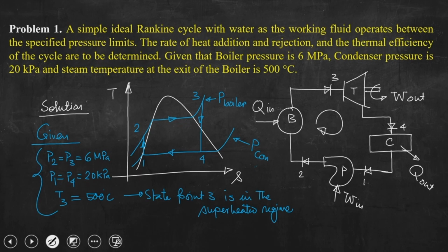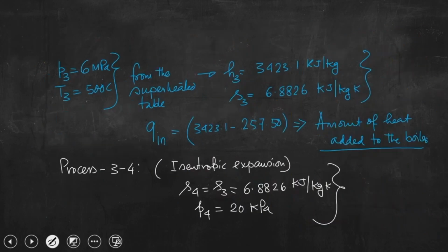So, it is a two phase mixture. You know that, as you have studied in thermodynamics, we know pressure and we know entropy at state point 4. By knowing this, we need to calculate what would be the enthalpy. So, what we can do very quickly, you know that total H is equal to Hf plus x4 into Hfg, right.